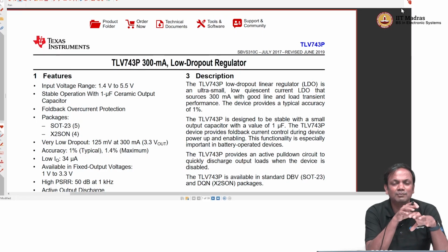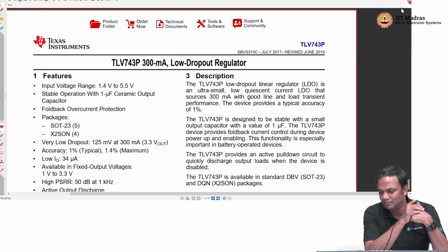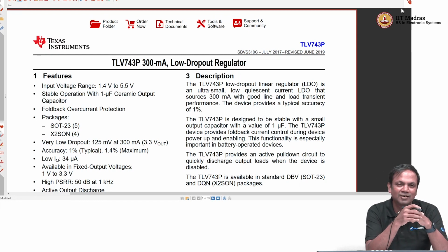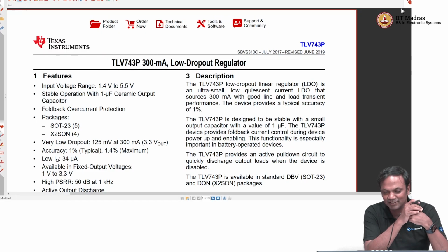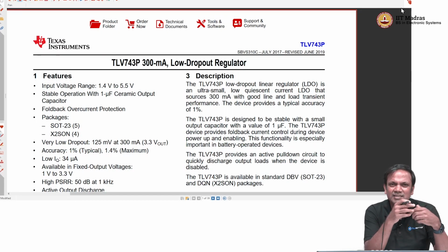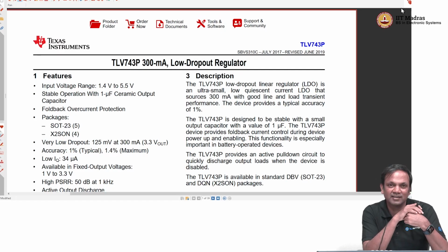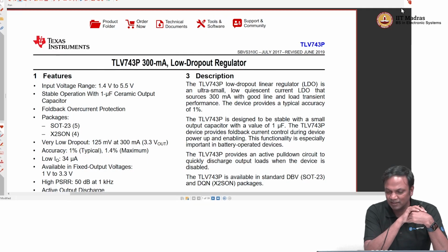So, please take the time to pick any data sheet for a component. If you have a bias towards data converters, then you pick up a data converter data sheet. If you have a bias towards regulators, you pick up a regulator data sheet. If you have a bias towards battery chargers, you pick that up. But please take the time to go through a data sheet and acclimatize yourself with, oh, these are all the things that typically get covered in a data sheet. That is a big step you can take towards becoming a good hardware system engineer for embedded system design.